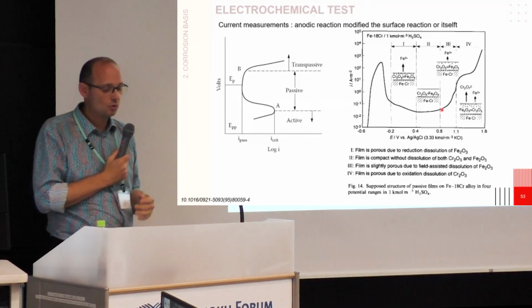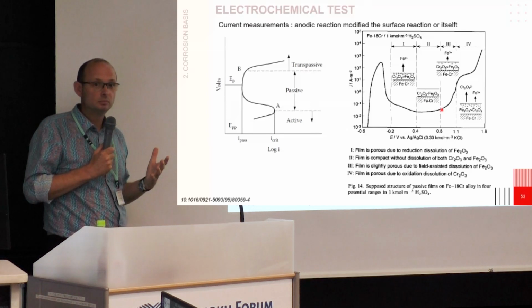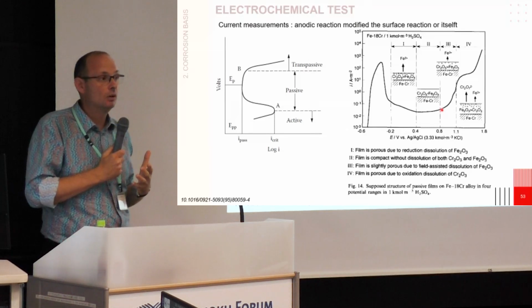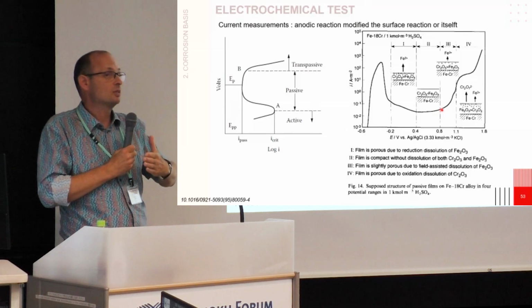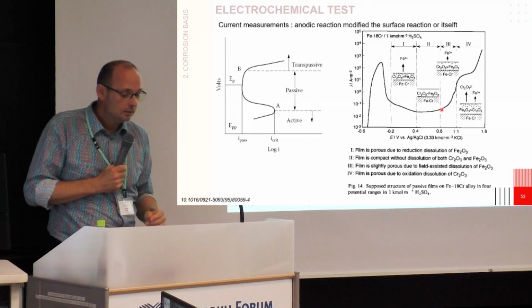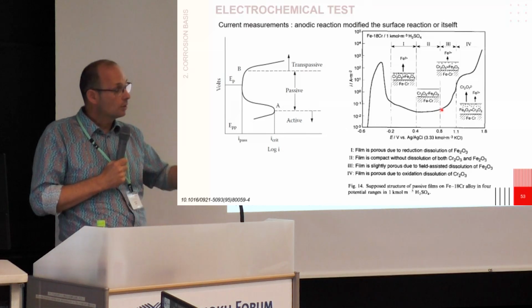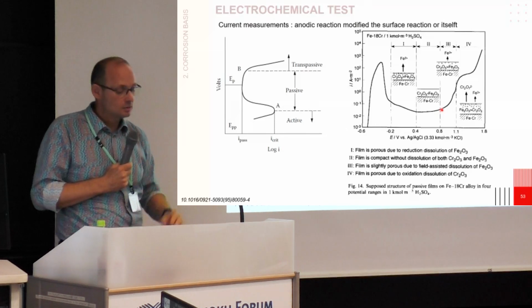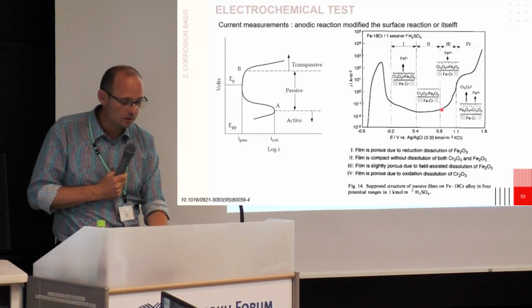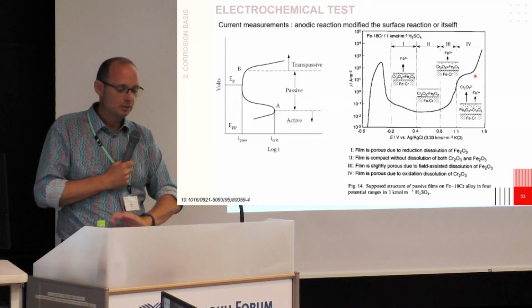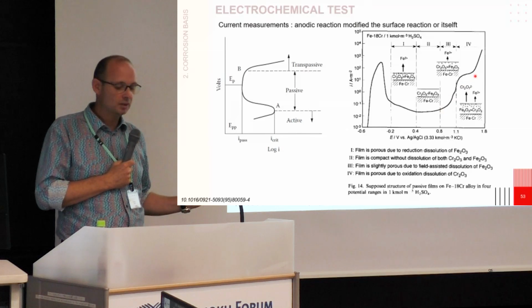However, when the potential becomes too high, the oxide layer cannot maintain its stability, so there is too much external force, and the currents start to be released. So the oxidation restarts, the dissolution of the metal restarts until there is nothing anymore that protects the material.